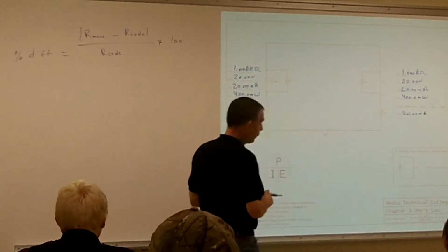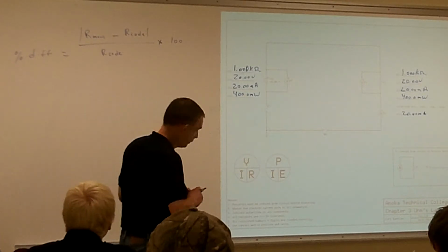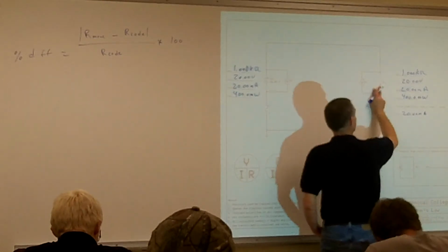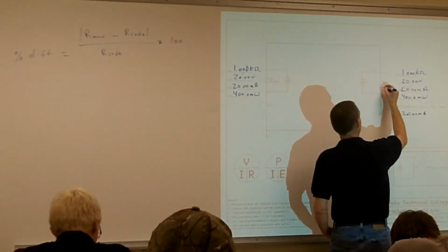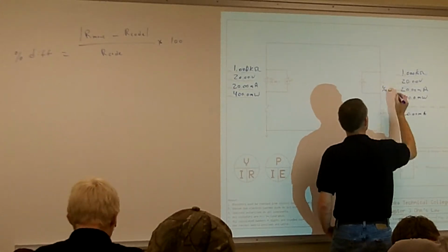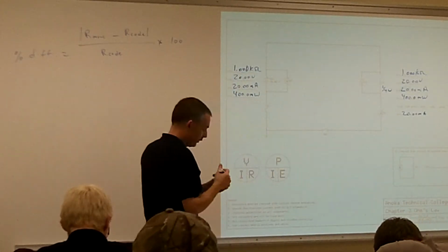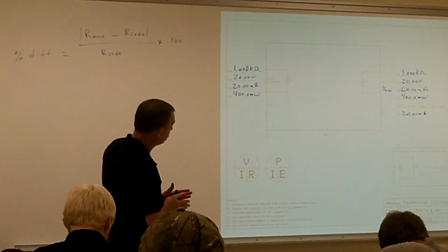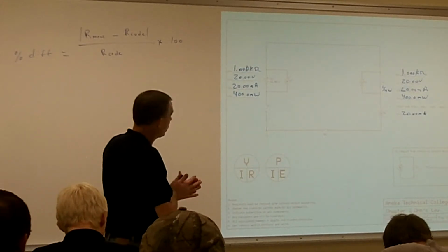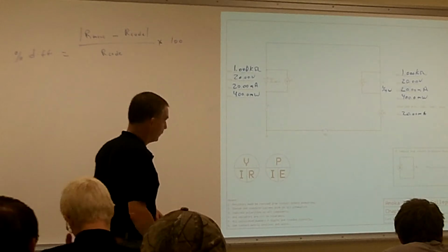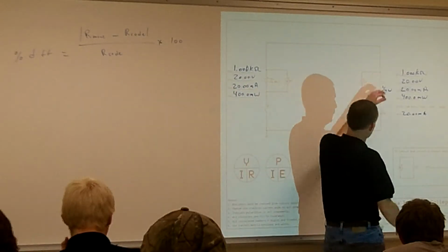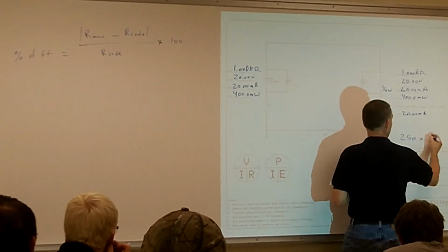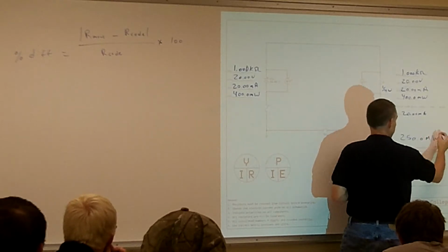Now there's another big concern. If we're talking about a single resistor in there, and let's say my resistor value was 1 kilo ohm, and let's say that the wattage of it was 1/4 watt. Okay, that's the rating of that resistor. I'm looking over on page 91 where they have the ratings of the watt resistors. If it's 1/4 watt, would that resistor be okay to use in that circuit? No. Because 1/4 watt is actually equal to how many milliwatts? 250 milliwatts. So I have 150 extra milliwatts that's going to really heat up that resistor.